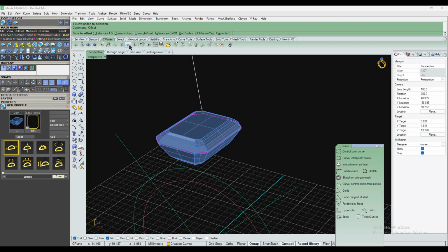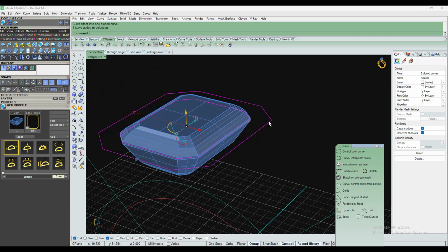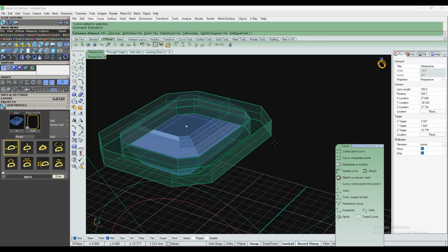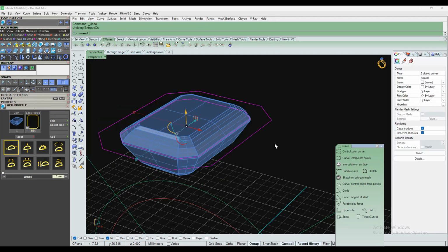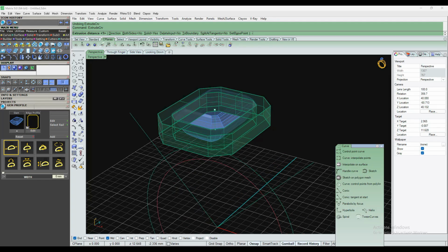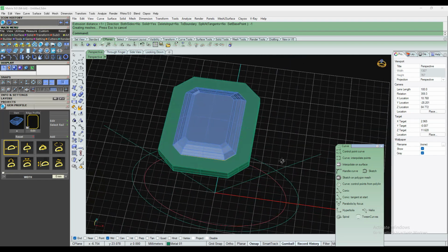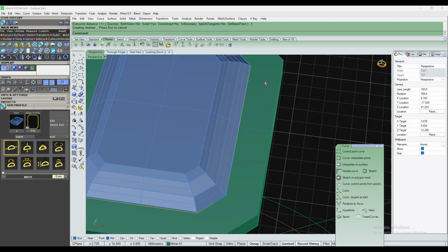If I'm going to use a 1 mm diamond or 1.2 mm, I can keep this distance as 1.5. So for now, let's make it a 1.4 offset. Select both of these curves, extrude, and specify a length of 1 mm. This depends on your parameters, meaning which parameter you are using. I want to change the direction, so let's make it -1, so it will go in the opposite direction, it will go down. Now I want to apply diamonds here.